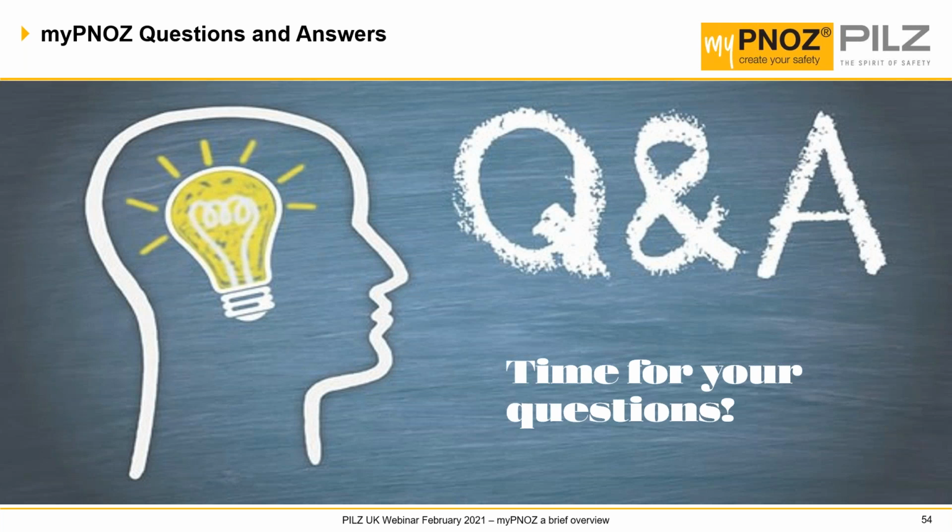Okay, so we have a question. With myPNOZ, does it only give a single output, or if you had 4 inputs, can I output each healthy input and an input for all healthy? Okay, you'd have to have separate zones. What you would do is have the inputs coming in and you can pass the signals through. So one zone would be an input, which would switch off the output. Second input would switch off second output, third output, and so on. And then you could probably use the second channel to come back into the first channel.